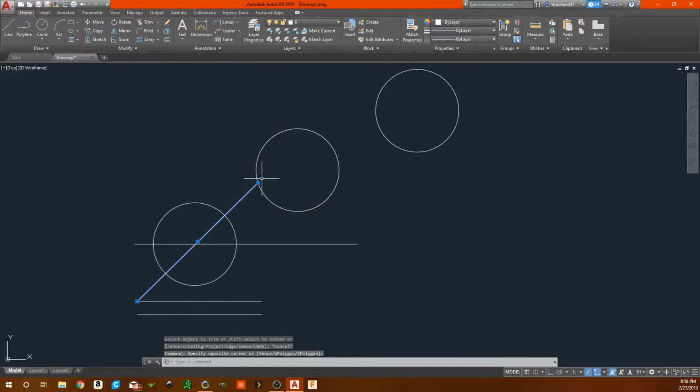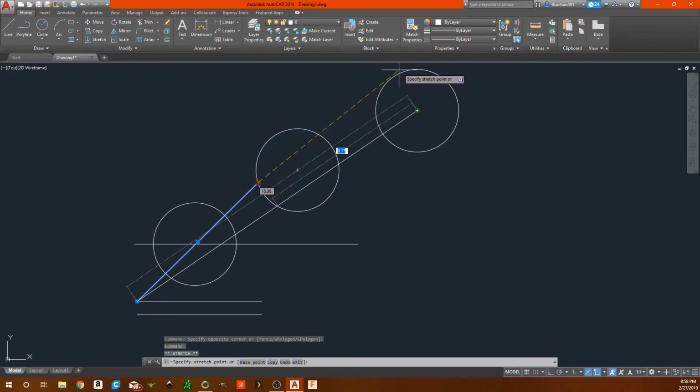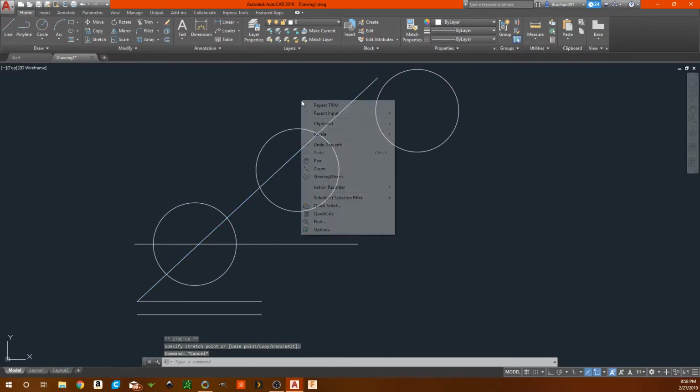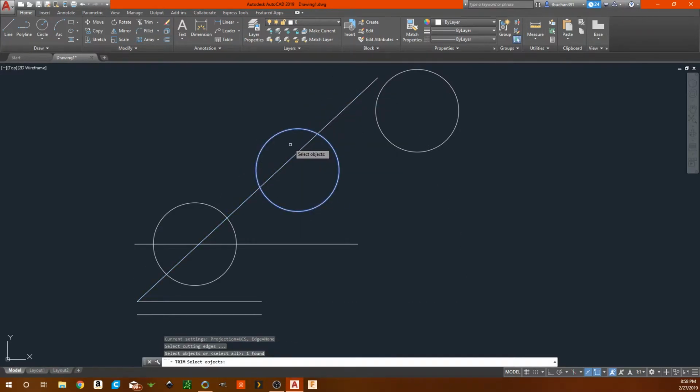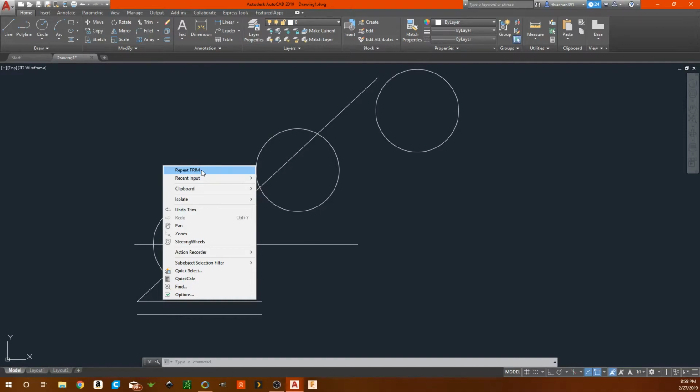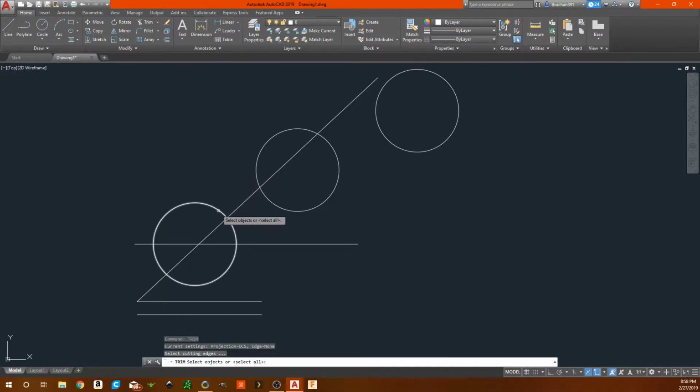Now let's get that a little bit farther out to where you can see how that actually does. And we'll start that up, select the circle, right click. Whoa. I didn't do that right, guys. Okay, let's do it like this. Trim, we'll select this circle, right click, and then see how it all disappears? That means everything past this line, this arc, will disappear whenever you click it.